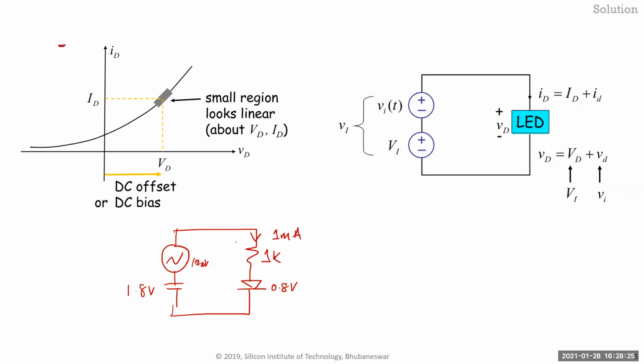And what you have done with this circuit is basically this: you've biased it at some point here, which in this case is like 1 milliamp, and then you're applying a small voltage again, which is through this resistor. Okay, so that way it remains very linear. Okay, and we'll show with some calculations why it is so linear. Okay, make sense?